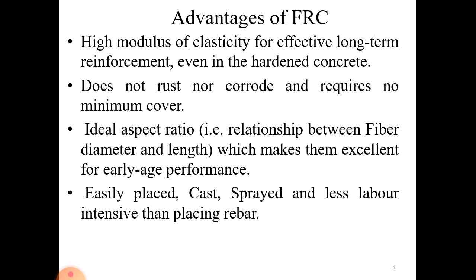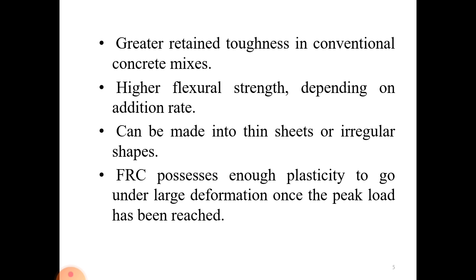Then another advantage is that it can be easily placed, cast, sprayed, and is also less labor intensive than placing rebar. Then it has higher flexural strength, depending on the adhesion rate. Then it can be made into thin sheets or irregular shapes, and FRC possesses enough plasticity to undergo large deformation once the peak load has been reached. So it can undergo large deformation.